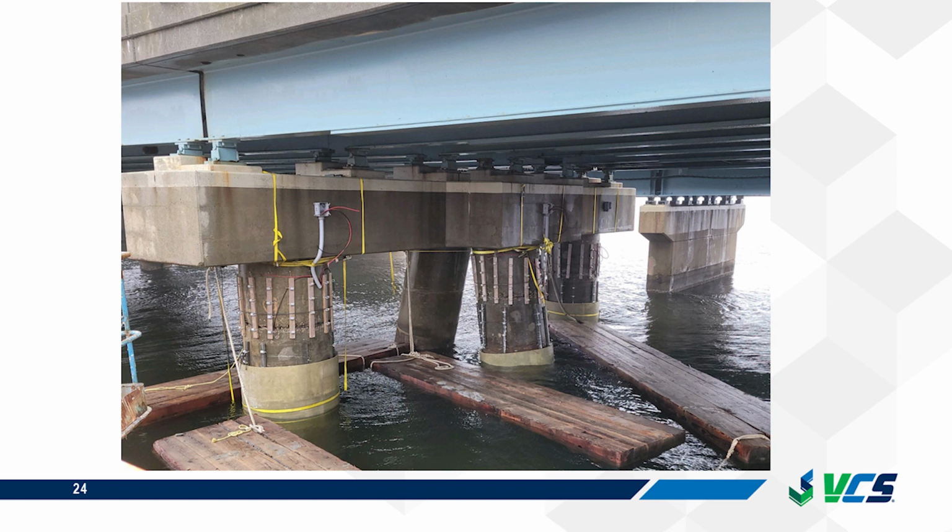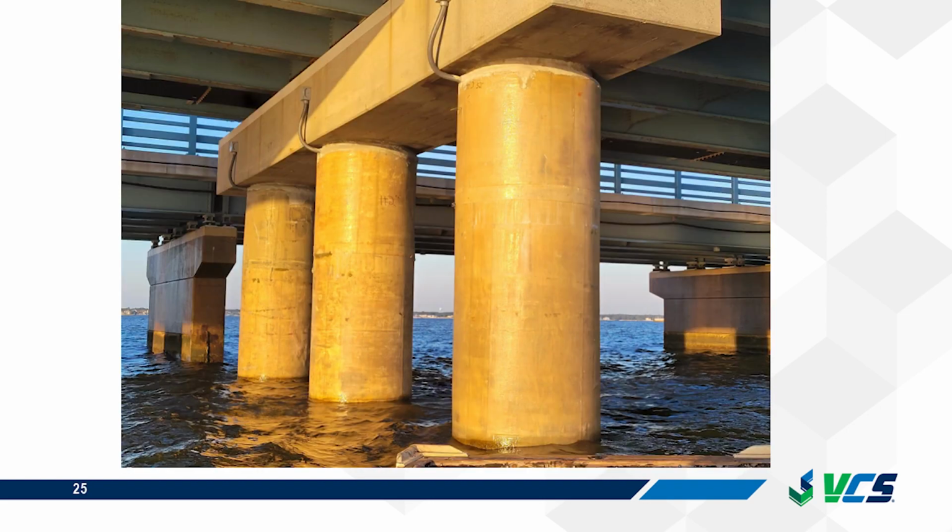And this shows you an example of actual jackets under construction. The anodes that you see at the top that are lighter colored are atmospheric anodes, and the marine anodes are a darker color, which you can see there. This is the FRP jacket that was installed on the bottom of the pile, but not at the top yet. And these are the monitoring boxes. And these are the jackets after they have been completed.